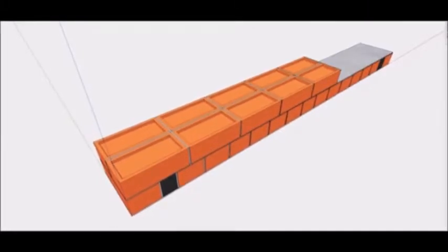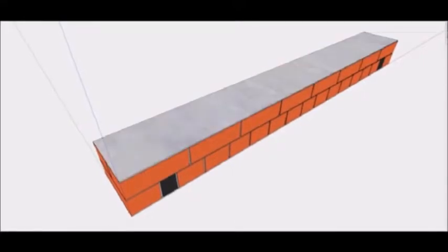Garden wall bonds are designed specifically to reduce the number of through headers, to minimize the labor in selecting bricks of roughly the same length for use as headers. The reduction in the number of through headers weakens the through bond of brickwork to an extent. This is of little consequence in a freestanding garden wall. Other combinations such as 2 or 4 stretchers to one header may be used.